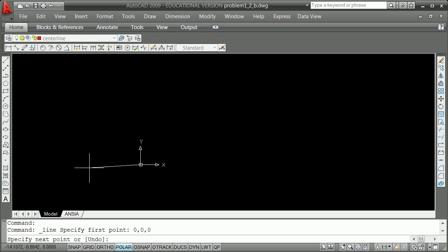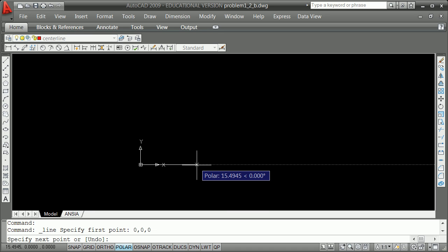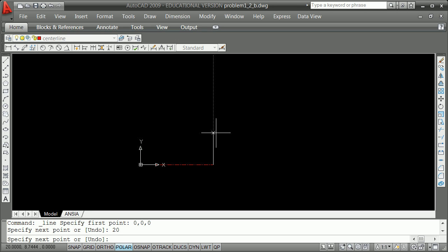If I can see it now, if I get my mouse anywhere close to where I want it, like at 0 degrees, I can then type in, and I'll just type 20 and hit a return. If I've zoomed out far enough, I will see it. If I'm not, I won't. That's why, in fact, it's better to use the typing at, the scripting, just in case you are zoomed out and you can't see what you want to do here. But you notice now I just give it a nudge in the right direction, type 20,